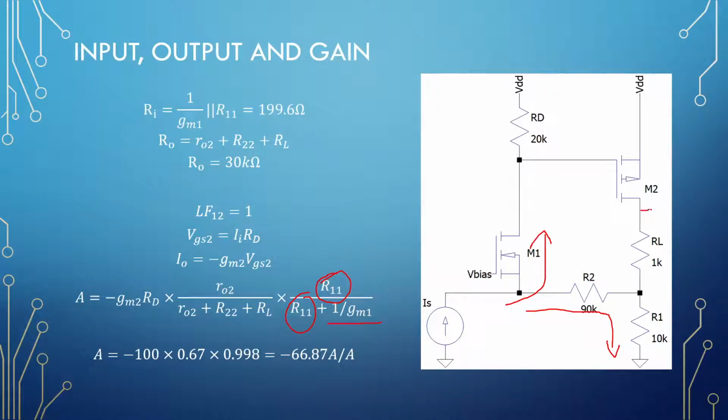On the output side, we have a current flowing in the MOSFET, which is the one we don't want, so Rout2 over everything else. So R load and R22 is in series with one another. So we want the current flowing in the load and the current flowing in R22 would be exactly the same. We don't want the current in the MOSFET. So Rout2 over Rout2 plus R22 plus R load. And that is our two loading factors or our two current dividers.